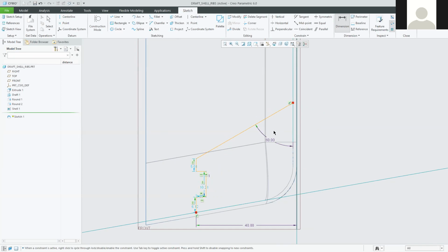So we're gradually building up the shape of this thing. This time I'm not creating new dimensions, I'm editing existing ones. So I want to hit Escape to get out of the dimensioning tool. I don't want to add some more in at this point. I just want to edit existing ones. So that one there needs to be 4.